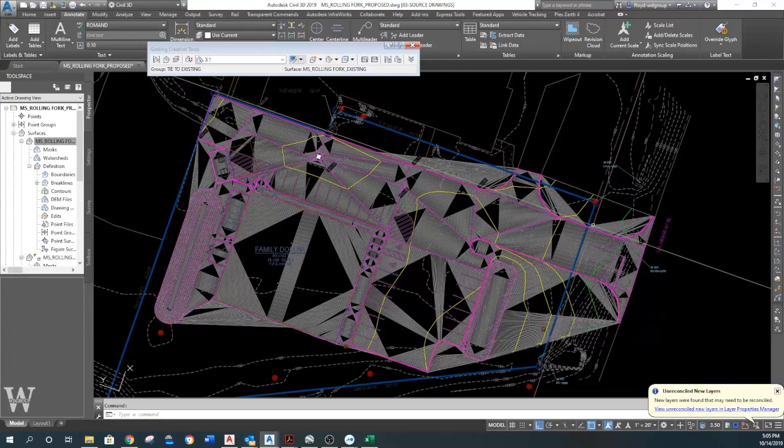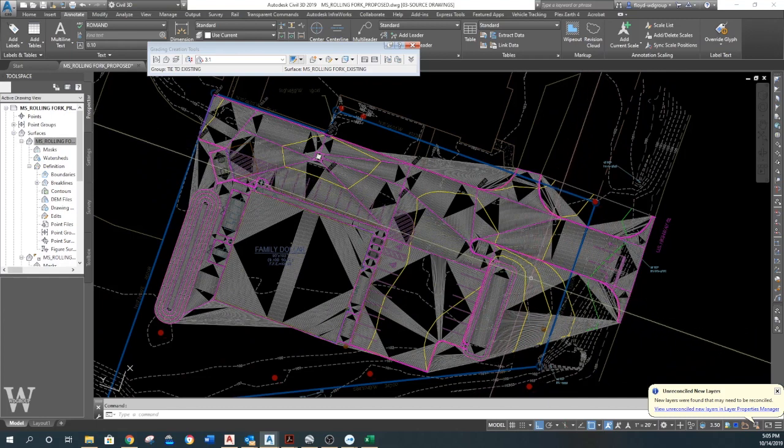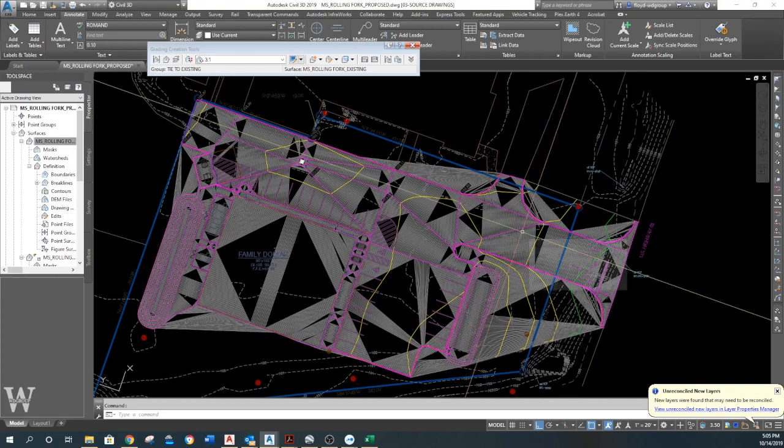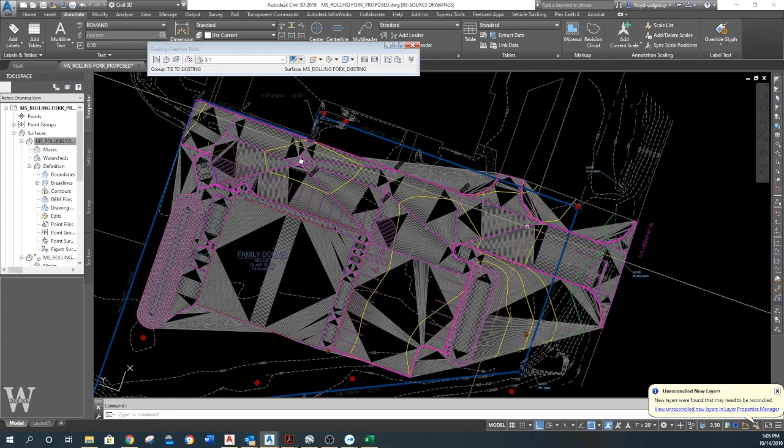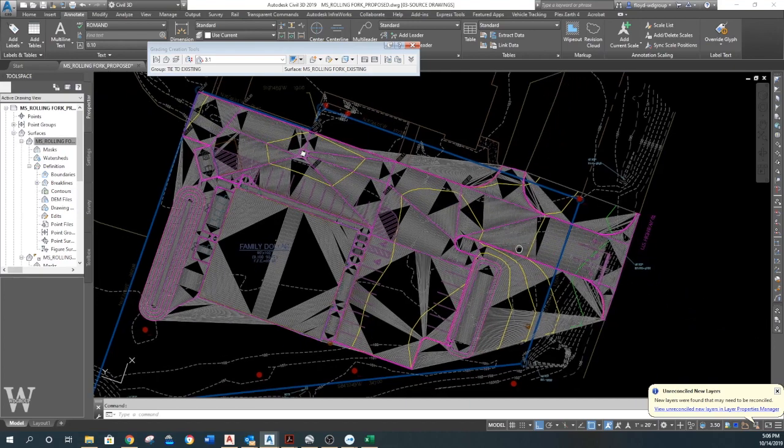So you can do these a couple of ways. You can create a boundary out here and define where your surface is, or you can delete triangles, which is what I usually do, because here's what happens. If you put a surface boundary on here, it never fails. You'll be almost through with your job, and you had somebody do something on that job, and they'll go in and delete your daggum surface boundary. And now you got to either figure out where it was, and you probably don't remember. So I try not to give anybody any way to mess that up.